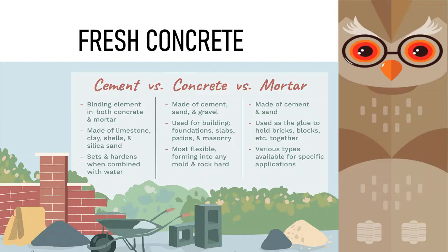For fresh concrete to be accepted, it should, number one, be easily mixed and transported. Number two, it should be uniform throughout a given batch and between batches of the concrete. It must have a consistency so that it can fill completely the form for which it was designed. Next, the fresh concrete must have the ability to be compacted without excessive loss of energy, must not segregate during placing and consolidation, and must have good finishing characteristics.